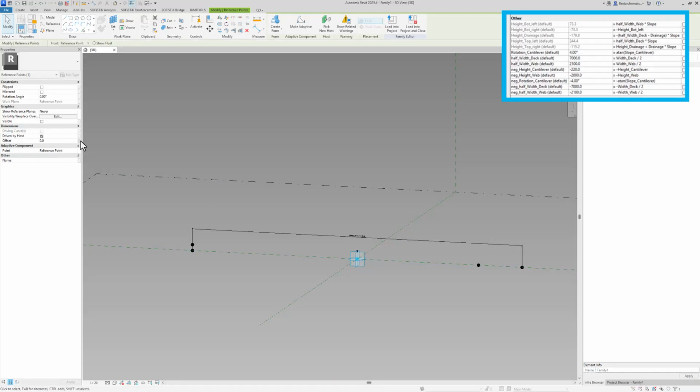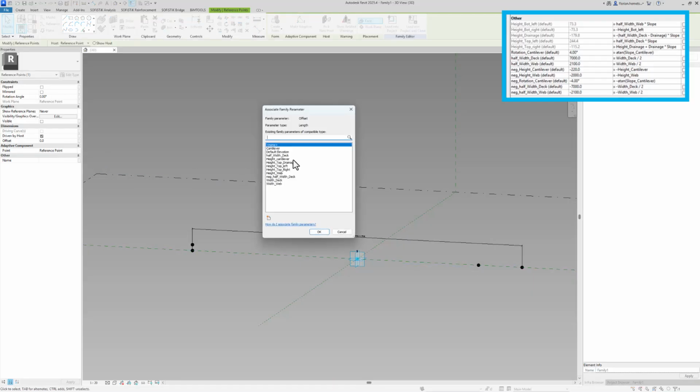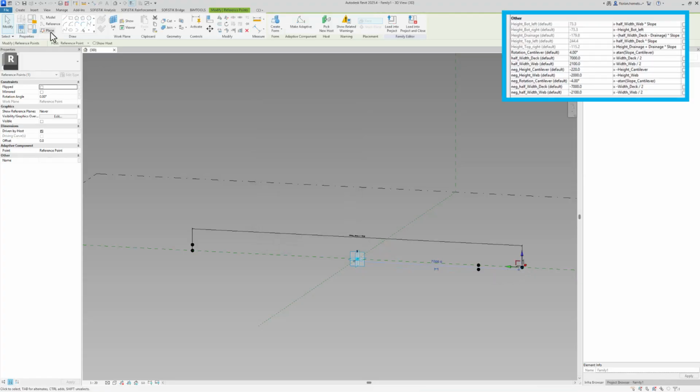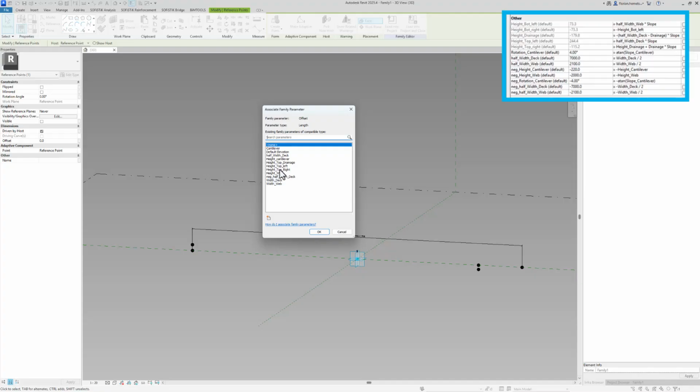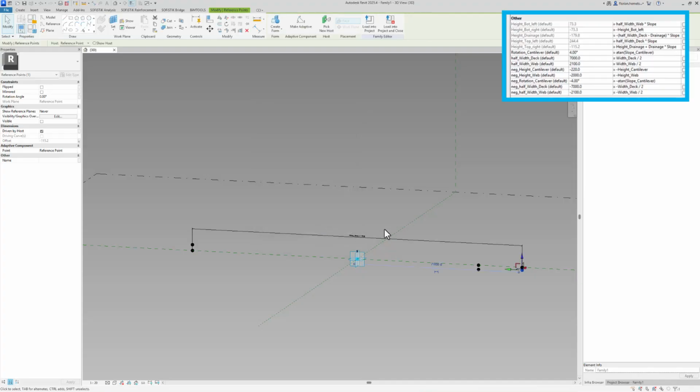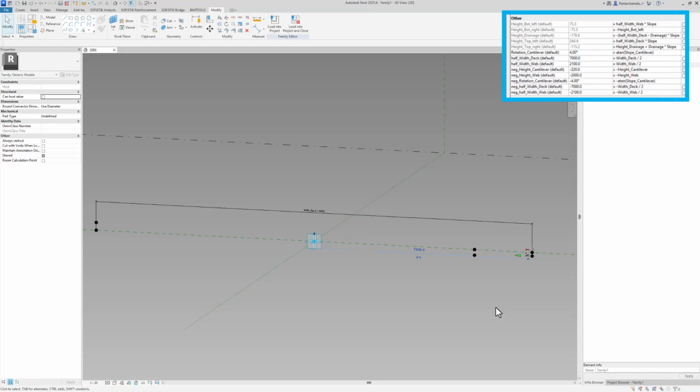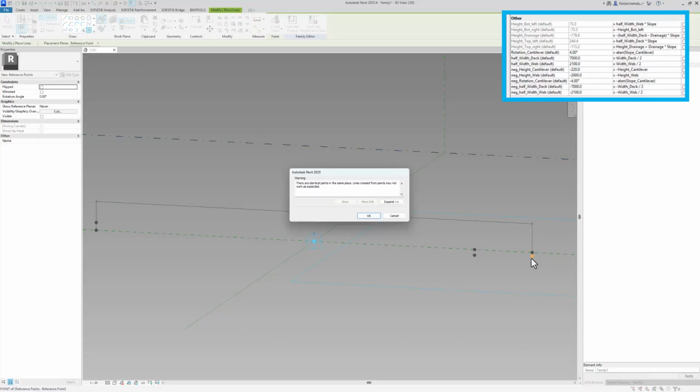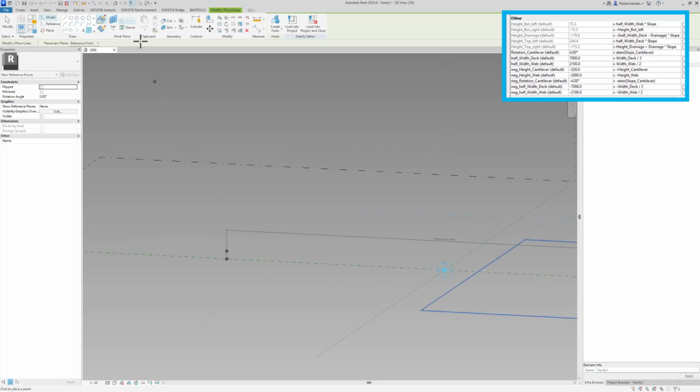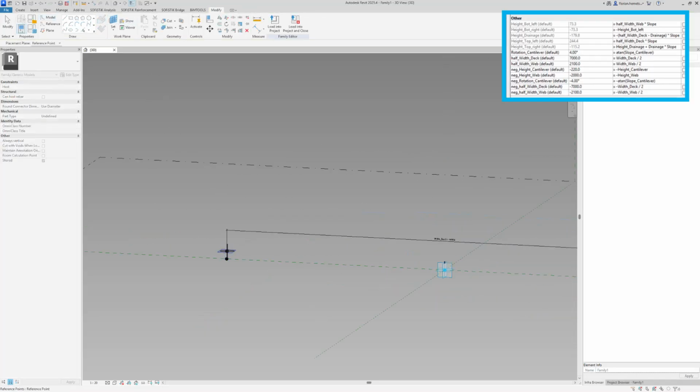Can select them now, and I can now assign the height of my drainage as well as the height on the top right. The only thing left to do here on the top is now to assign the thickness of the cantilever, which I called the height of the cantilever, which is reference to the most further out point here, as well as to the left one.